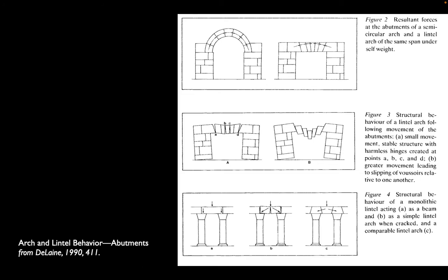And they were sophisticated enough to develop what's called the flat arch, which you see in the upper right, where even though it looks like a straight rectangular beam, the shapes of the voussoirs essentially introduce an invisible arch, right? An arch that is perpendicular to the line between each voussoir. And instead of geometrically getting out of the tensile region, it's just taking advantage of the equilibrium definition of an arch.